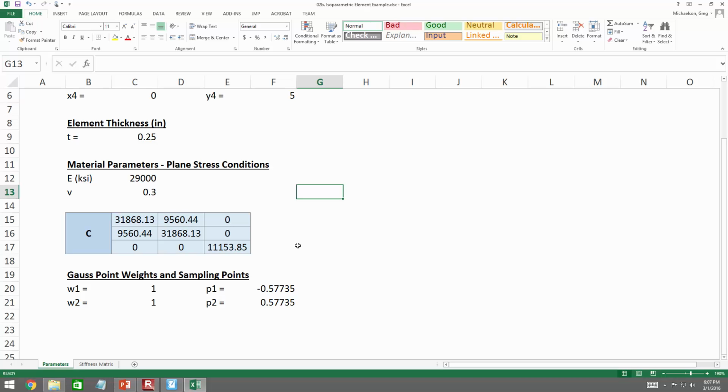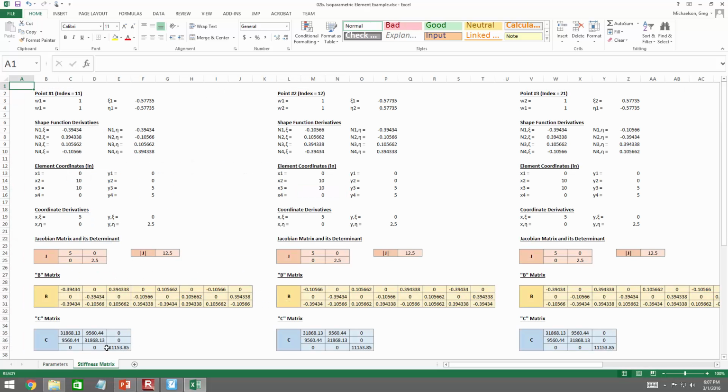So what you see on the next page, I know it seems like a mess, but look at this. I've got this split up into columns. All of this is my first term. All of this, my second term. All of this, my third term. Do y'all see that? Okay, so look at the indices up top. Look at my Gauss points and see how I cycle through all of them, all the permutations. It's like that Gauss integral we did, it's just blown up a little bit.